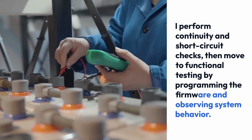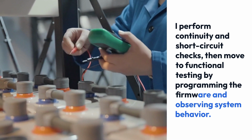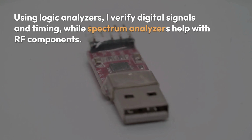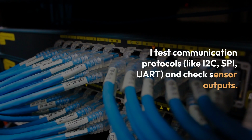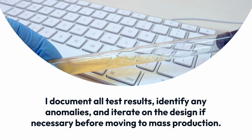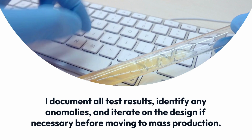I perform continuity and short-circuit checks, then move to functional testing by programming the firmware and observing system behavior. Using logic analyzers, I verify digital signals and timing, while spectrum analyzers help with RF components. I test communication protocols like I2C, SPI, UART, and check sensor outputs. I document all test results, identify any anomalies, and iterate on the design if necessary before moving to mass production.